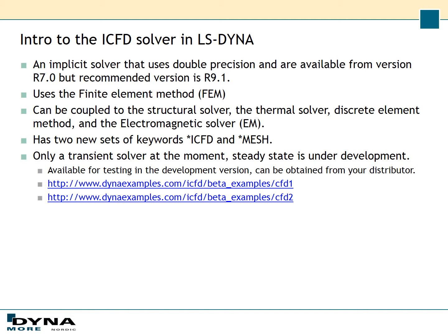The ICFD solver is a CFD code that uses double precision, and it's an implicit solver, and it's available from version R7 of LS-DYNA, but I recommend to use the latest version R9.1. And it uses the finite element method, and it can be coupled to the structure solver, the thermal solver, the discrete element method, and the electromagnetic solver. And you can also combine several of these different solvers, so you're not limited to only couple two of them.